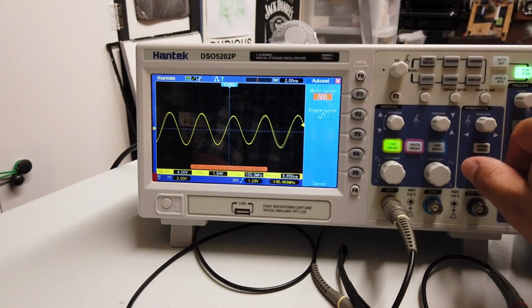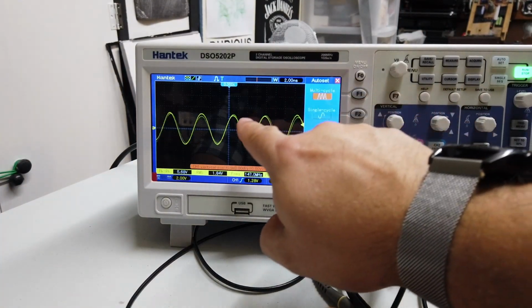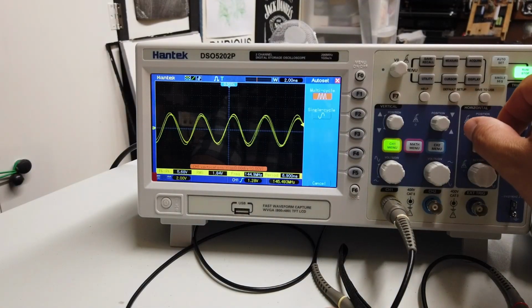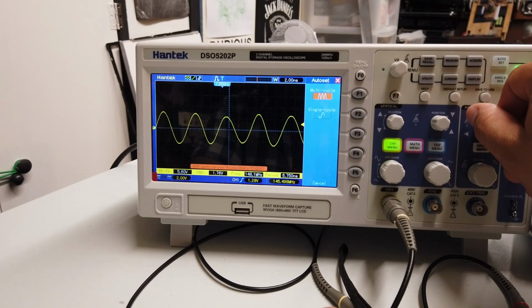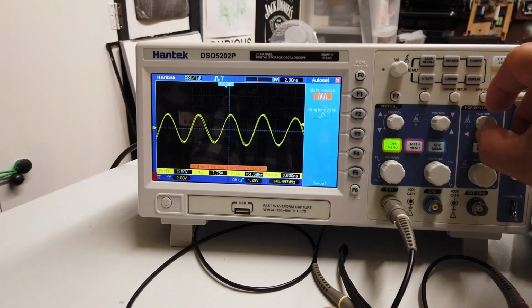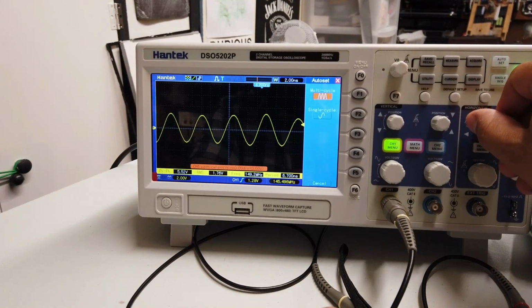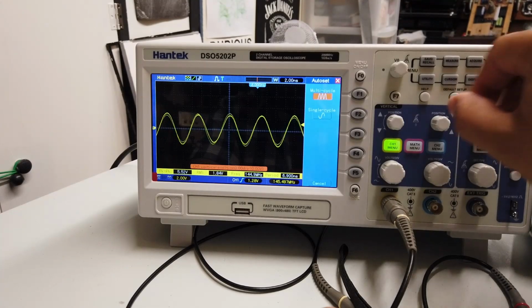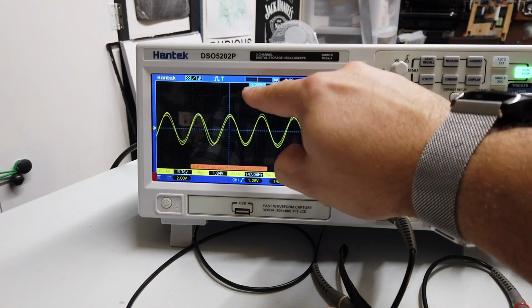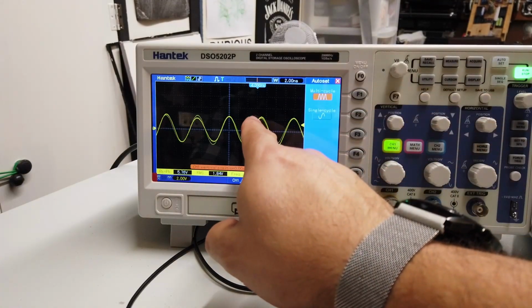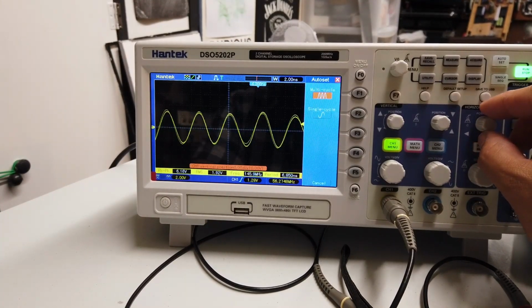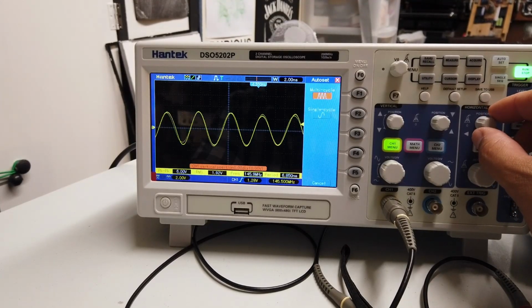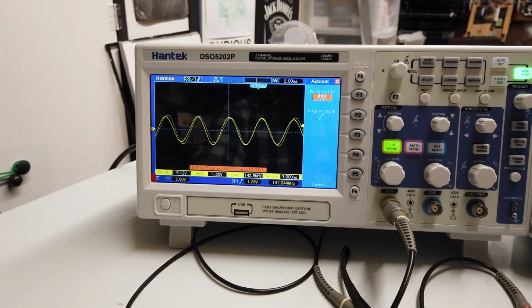Now, we also have the scope set to 2 nanoseconds per division. So if we just position that horizontally, there we go. Position that there. Okay, so offset it. And we can see up here, that suggests that is 6 nanoseconds to this point here. Let's just get that exactly where it needs to be. And that looks about right, 6.3 nanoseconds.